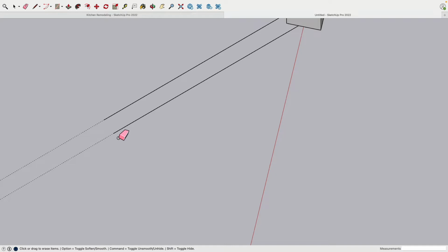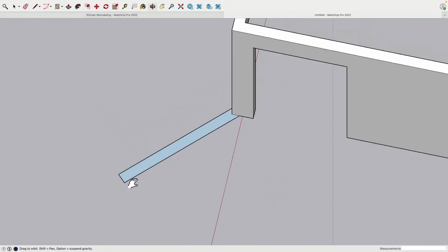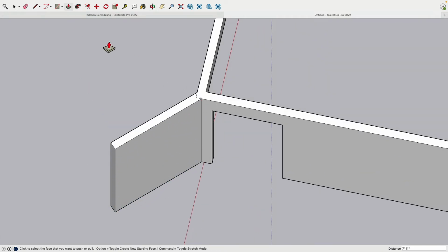Clock removed. Yeah, cool. Let's say we are just removing all this. I want to show you an additional trick. We want this line to be really 90 degree. We just draw an extra line. This extra line, now we can select and rotate exactly 90 degrees. Then there where it intersects, there we continue drawing. You see, easy peasy. And then this whole thing, we bring up,